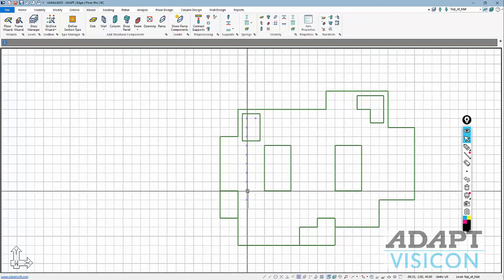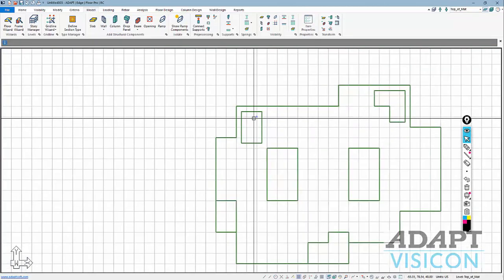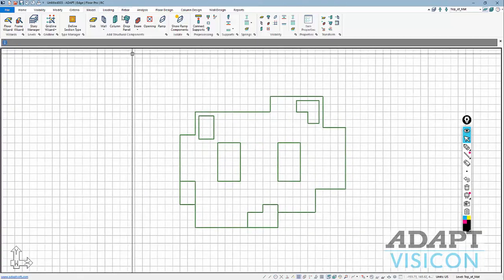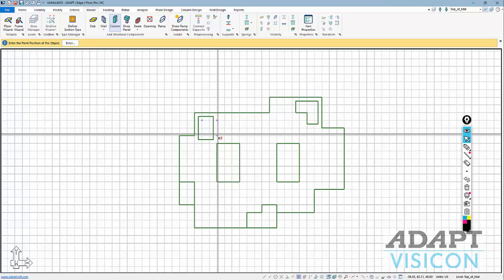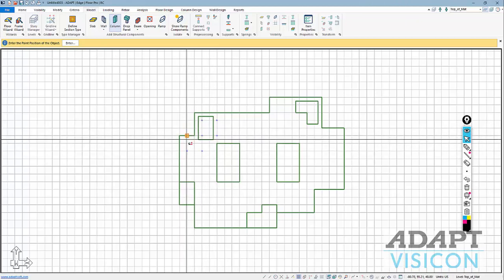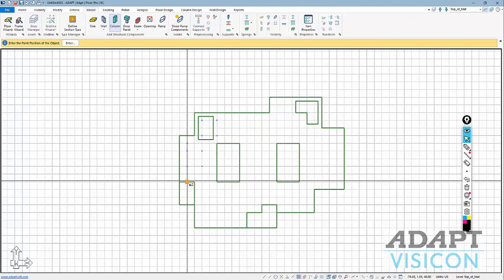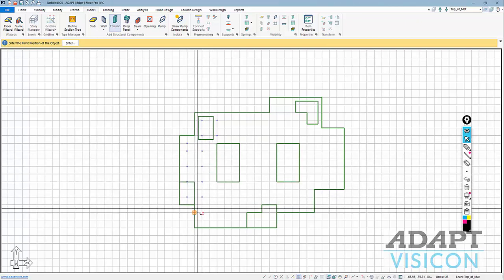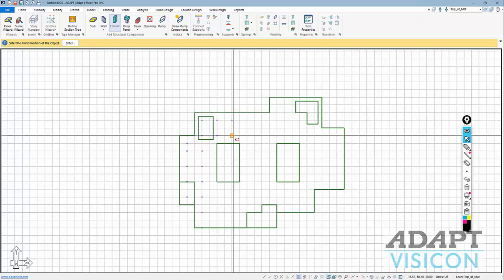This is going to be a lot of piles. In fact, let's space them at 20 feet on center, just for sake of the example here and expediency. So we'll do a pile here, kind of in this form. We might have to add a corner pile, for example, there in some spots, but we'll go through this model and begin adding all of our piles in the structure.